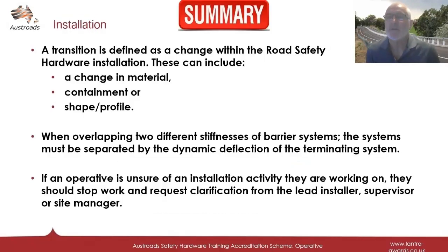In summary, a transition is defined as a change within the road safety hardware installation. These can include a change in material, containment, or shape/profile. When overlapping two different stiffnesses of barrier system, the systems must be separated by the dynamic deflection of the terminating system.